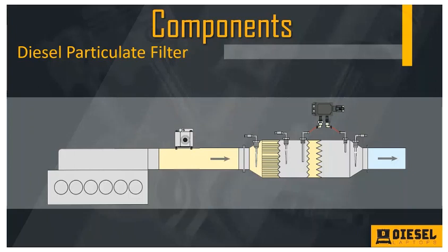Now, the problem is if your DPF assembly is working correctly, it's going to mask that, right? So you could have an engine that's smoking, and you might not be able to tell because your DPF is capturing all that. So that's the problem. You might have a smoking engine, something's wrong, and they never realize it because they never see smoke, so they just keep driving. The next thing you know, he's derated, he's sitting on the side of the road, and he can't go anywhere because his filter is completely stopped up with soot and ash, and his regeneration system can't overcome how much is going downstream, right? So just something to be aware of.